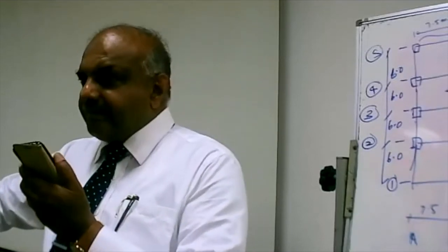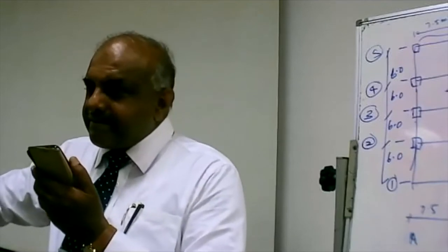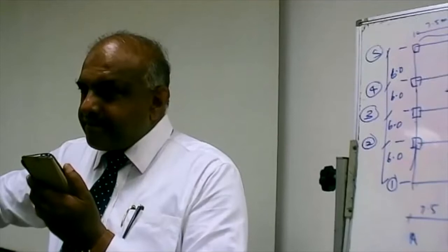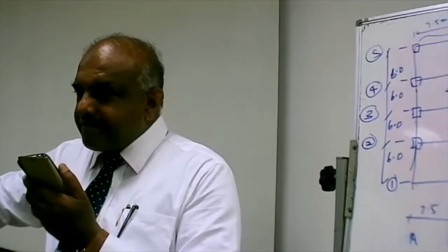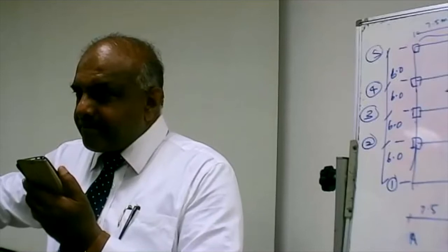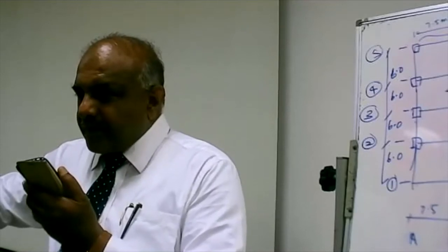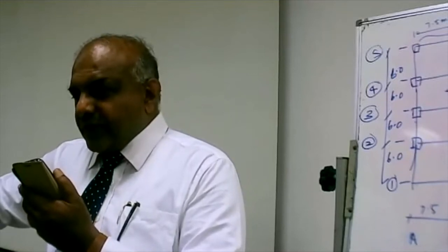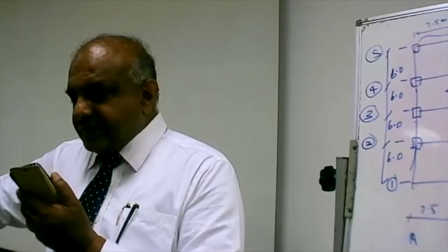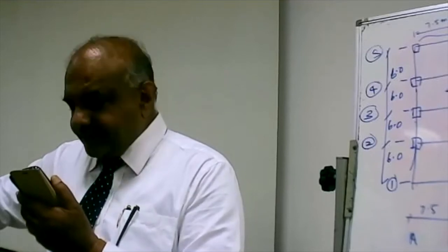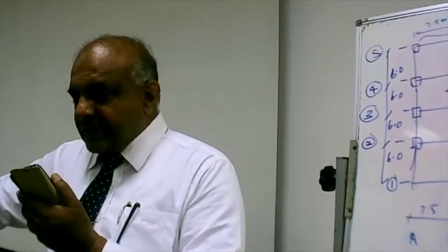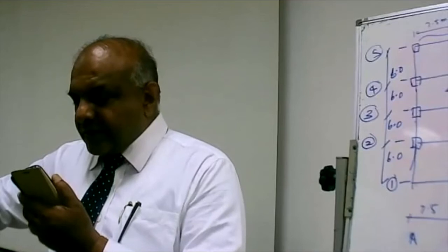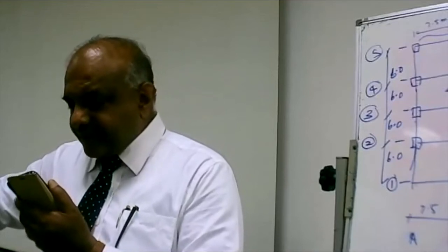Any other question? Yeah, can't we consider the combined second moment of inertia of the core wall? Because here you consider only the major direction, the minor direction you didn't consider. So can we consider the combined? But if you consider the way that it's twisting, it is easier to consider only the walls in the major direction only, because it's a 10-story building.